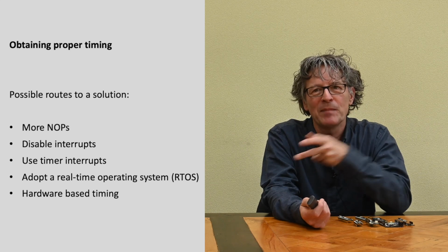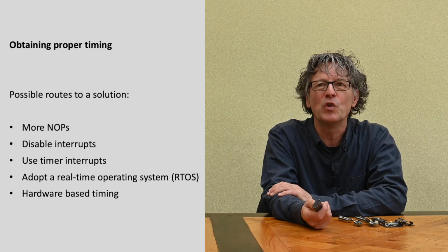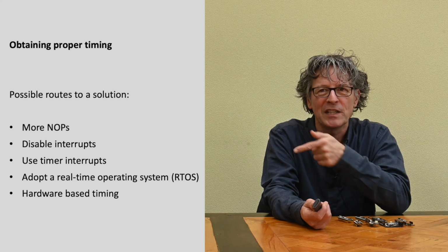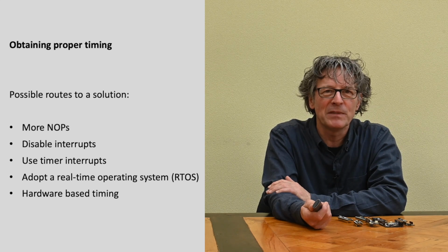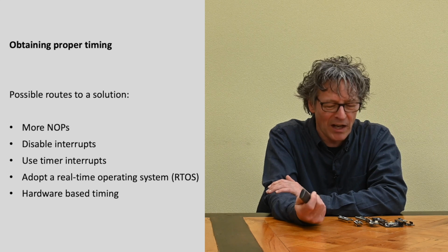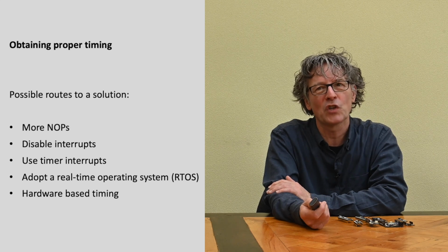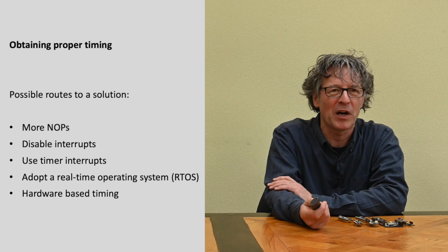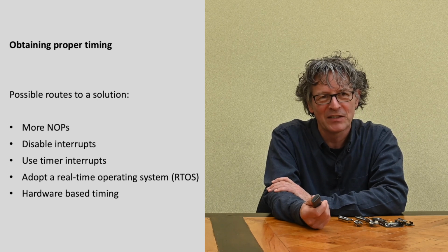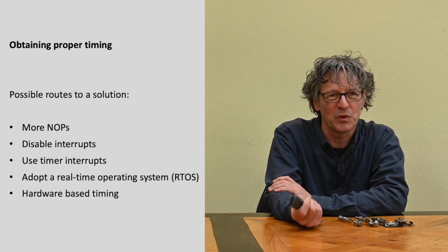The second thing is to disable all the interrupts, in case you write code without interrupts, so you get rid of the housekeeping things. That is advised by a number of websites. I played a little bit with that. It doesn't reduce all the timing problems, and on top of that, it can also create serious issues like non-responsive devices and not being able to reprogram your Arduino anymore, etc. So I didn't want to go too much down that route.